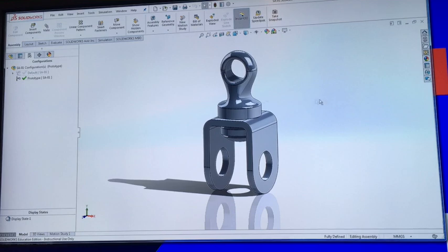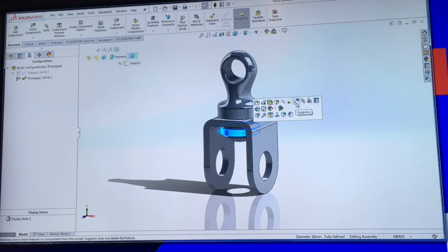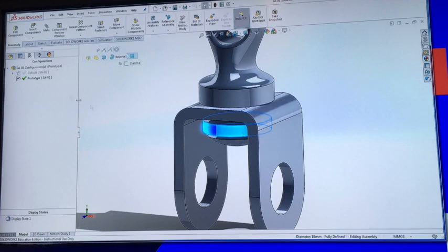So in our prototype version of this part, we're going to have a customized pivot pin. And also we're going to have no washer. We're actually going to add in a split pin, which looks a little bit different. So in this prototype version, you can suppress the washer.